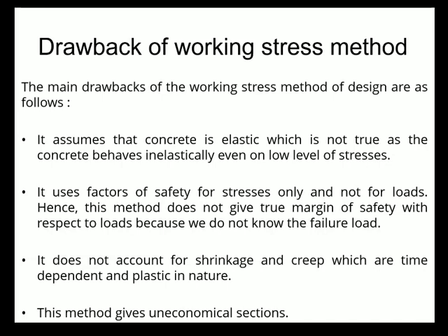And then after all, whatever we have discussed, the stress strain carrying capacity of most of the fibers except the top fiber under bending is not utilized. Therefore, the entire design becomes uneconomical. That means we could have reduced the section size if we would have been able to use the fullest stress strain carrying capacity of the lower fibers, the fibers near the neutral axis. Then of course our dimensions would have been small, but at that time it was relevant, because we didn't have the idea about the stress strain characteristics of concrete and steel, and so we continued with that.